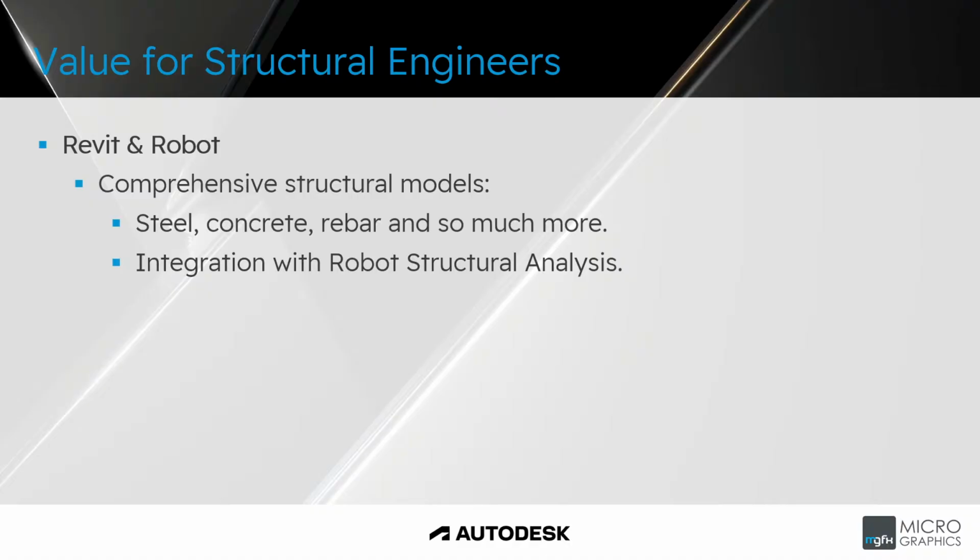And the analytical functionality within Revit has been built upon. So you can now do your loading, I think load combinations as well, if I have it right, which I would not recommend at this stage because you have to go and undo it in Robot anyway. Okay, so that's just something to keep in mind. But I think it's giving us a bit of an indication of where they're going with Revit, but we're not 100% sure at this stage.